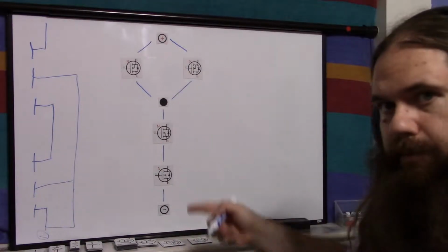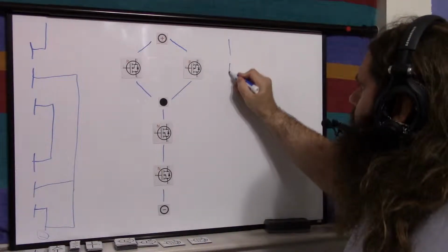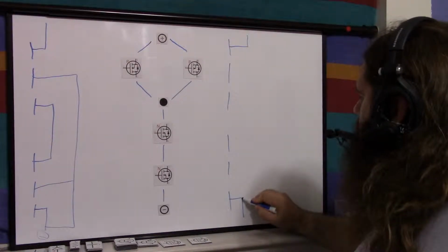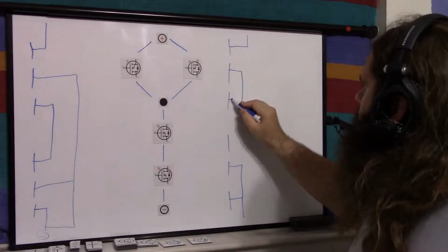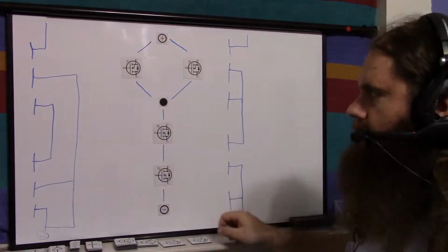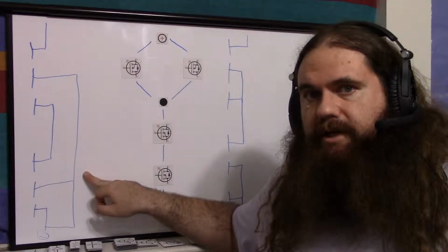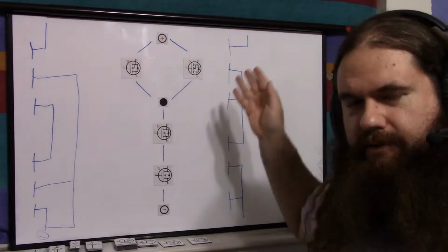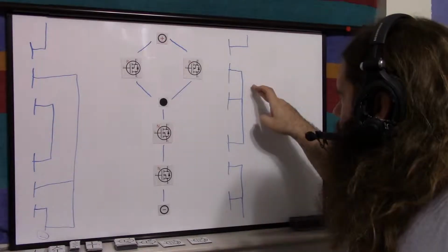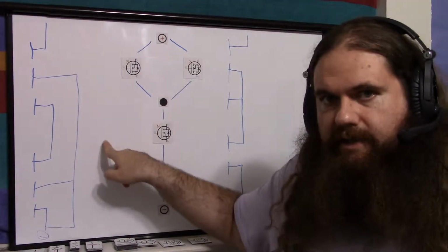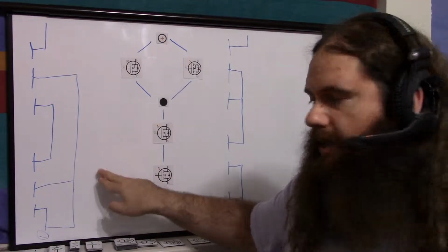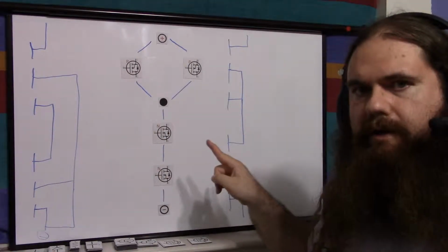This is the way you'll actually see it drawn. The way we have it hooked up with discretes is more like this. So we've got our 3, and we've got our input, and then we've got our output, but our substrates are tied together. So it's like this. So this is what we actually have, without worrying about the body diode. This is kind of how you'd have it in a chip. This is kind of how you'd have it just putting them in a breadboard. And I've tested this. This works fine. You connect them like this. And even though the sources and the substrates are all connected, this diagram is not the same as this diagram. These are different wirings, but it works.